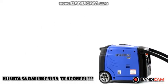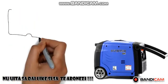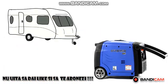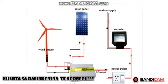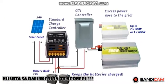Off-grid inverters can also be made for portable use, while grid-tied inverters cannot. Therefore, inverters that are labeled for use in caravans and motorhomes are off-grid inverters. A grid-tie inverter, on the other hand, can be directly connected to the solar array and the grid. There is also sometimes charge control option in the grid-tie inverter, and therefore some variants can also be connected to the battery pack. In other words, a grid-tie inverter can become the central component of a PV system.